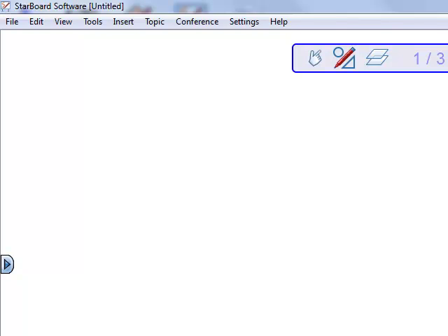The fabrication detail for a column contains orthographic views of the column, locational dimensions for plates, angles, and holes, length dimensions, base plate configuration, connection specifications, and miscellaneous notes. And the beam has a slightly different set, some of the same, some different. They have orthographic views, sections or end views when required for clarity, length dimensions, locational dimensions for holes, angles, plates, cutouts, connection specifications, and miscellaneous notes for the fabricator.